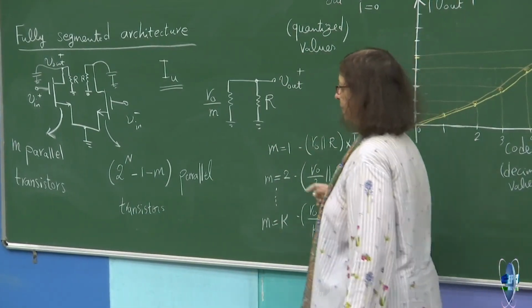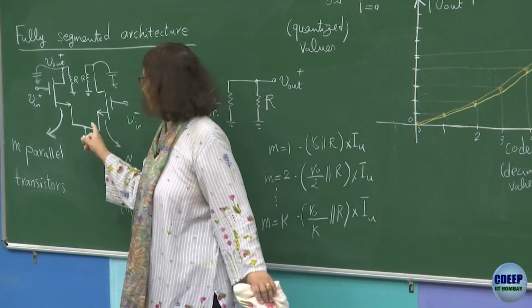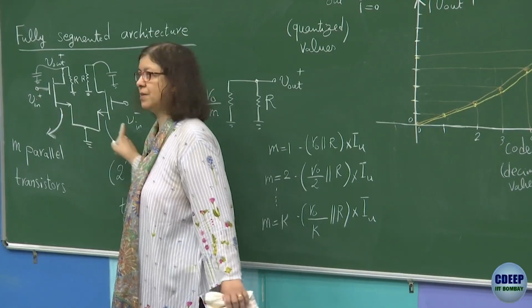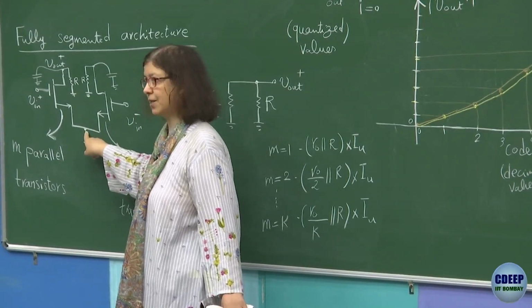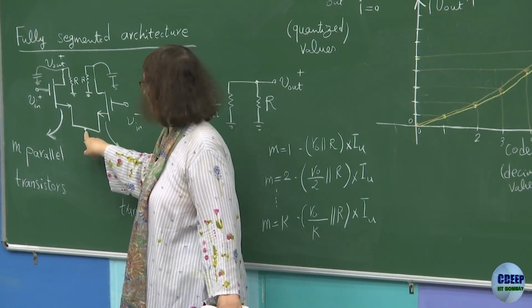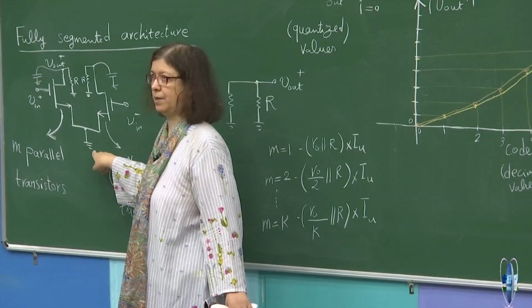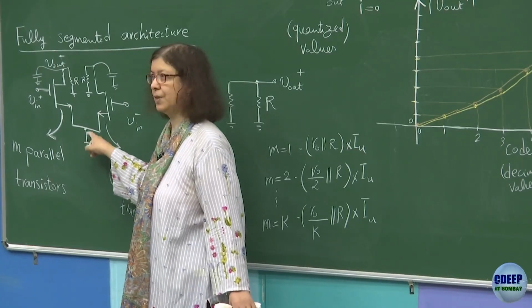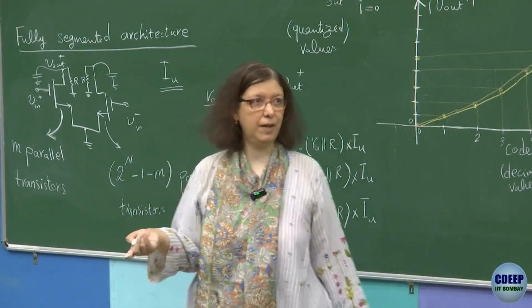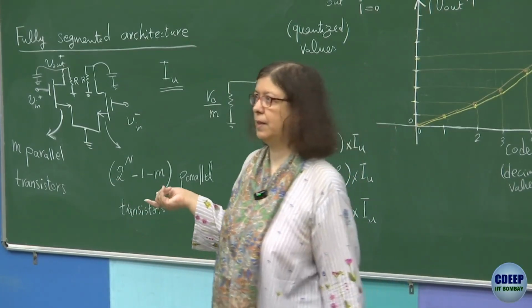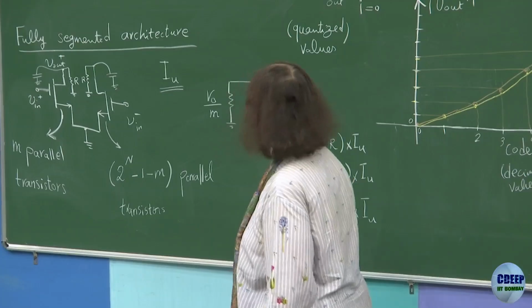Another problem that we have not discussed is that these two inputs are not synchronized well. Because of that, this node is not actually a ground, and there is a capacitor here. It's not ideal. And you know that the capacitor here increases the effect of the common-mode level, right? You have learned this in the analog course. So it's a very important point.